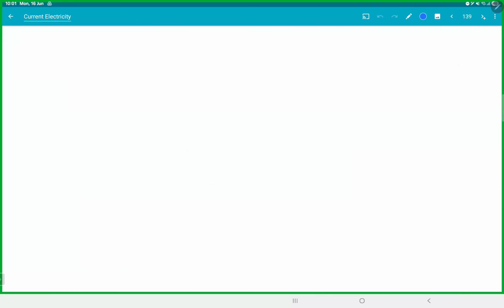Next thing, to find the internal resistance. So we got EX, we want to find RX now. Now what you do, close the switch and balance the bridge.